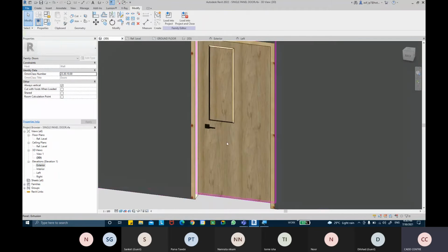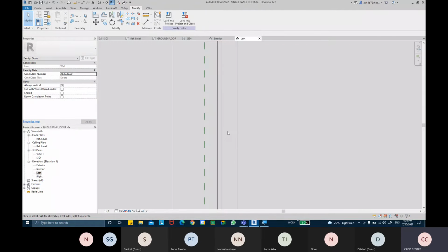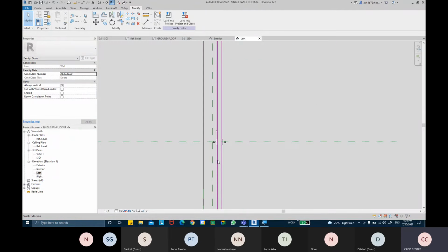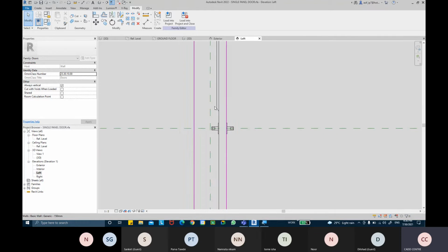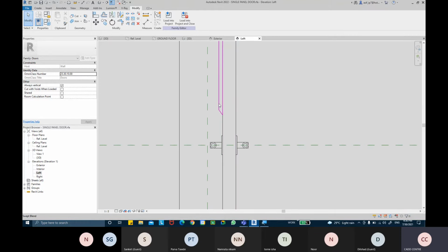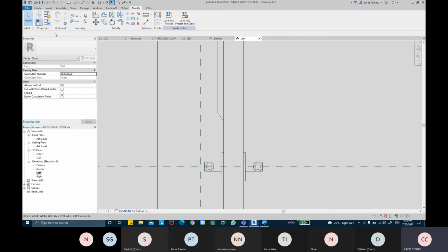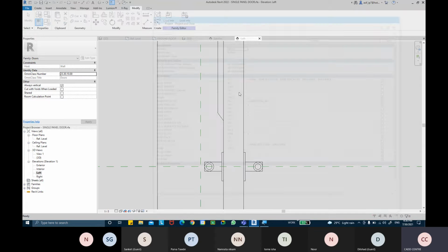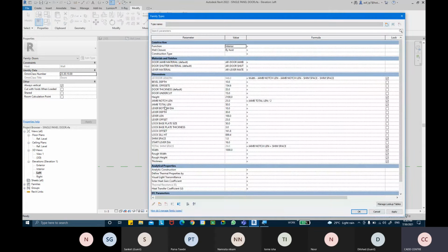Yes, come into left view and create. So from this side to there. So it will start from that end. So this is 10 mm of depth basically, which you can control also. So yeah, I did it on the external side. If you want to create on the internal side, you have to come to the internal side. So bevel depth that is 10 mm.